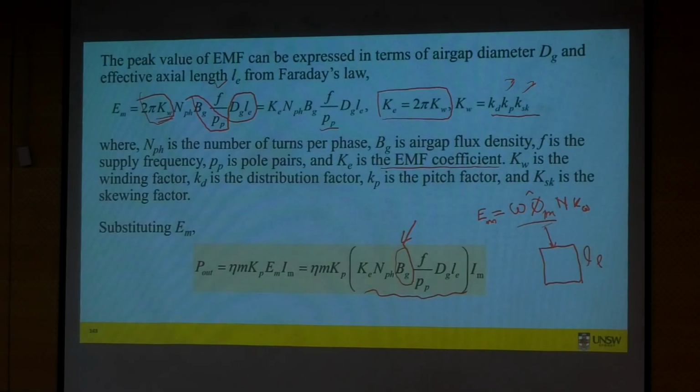That's what we should always do as a first step. But at this stage, we still do not know our geometry, so we haven't gone to finite element yet. So at this point, we can simply estimate or assume BZ. What is the typical BZ I'm expecting? Maybe I expect it to be 0.8, maybe 0.85, so around that value. I may assume it at this point as, let's say, 0.8.